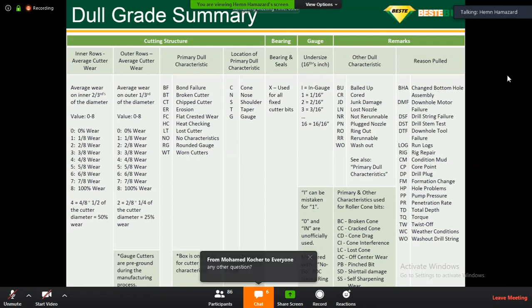We can gather them in real time. That means while we are drilling, we have all those data. And we also have another set of data, which is in the memory mode. So we have a battery and memory in the LWD tools. Once we pull out the tool to surface, we can download the data, and then we correlate them with the real time. They are very reliable data, and it gives you a big favor in terms of delivering your well.